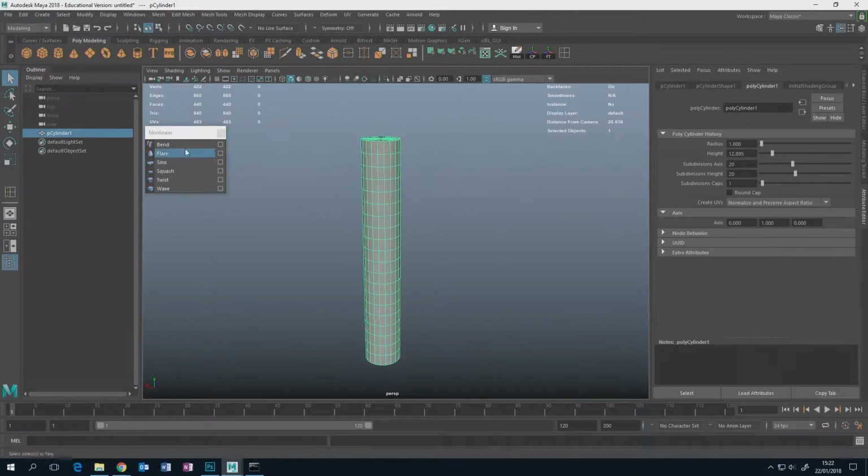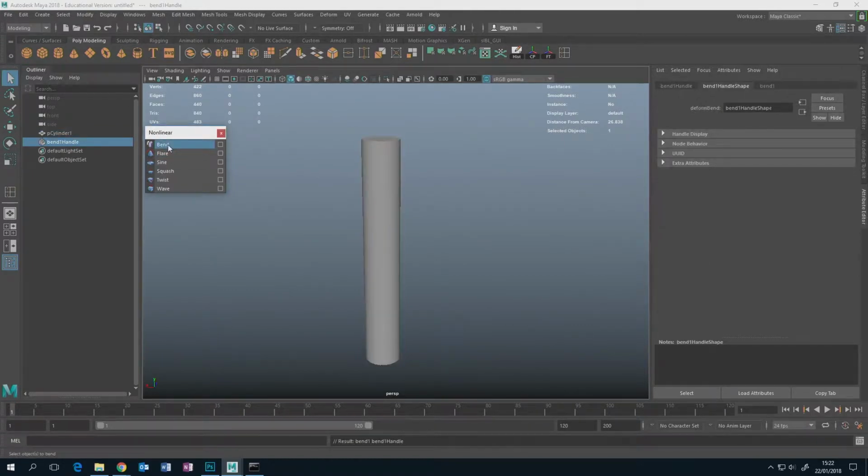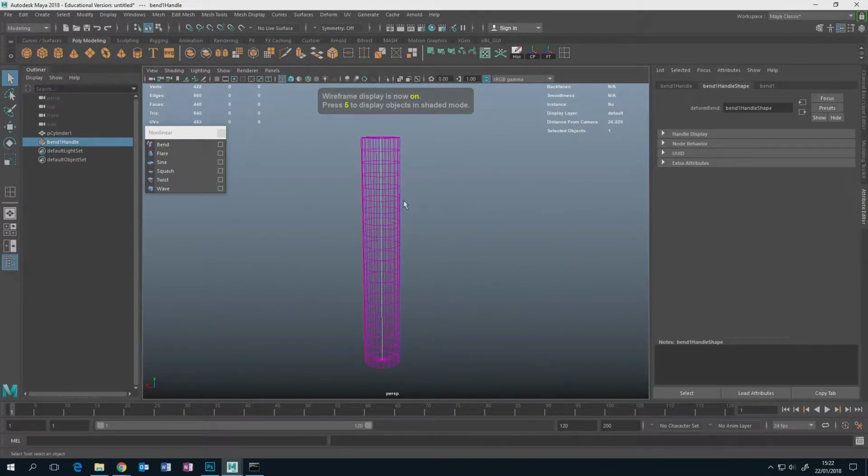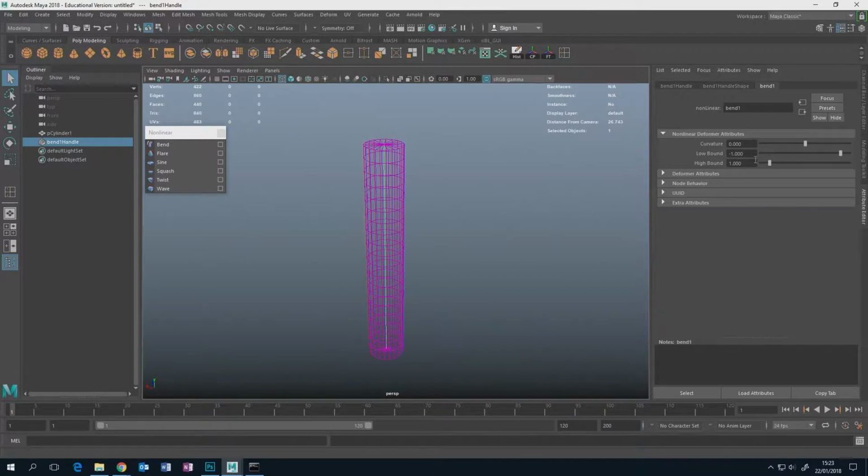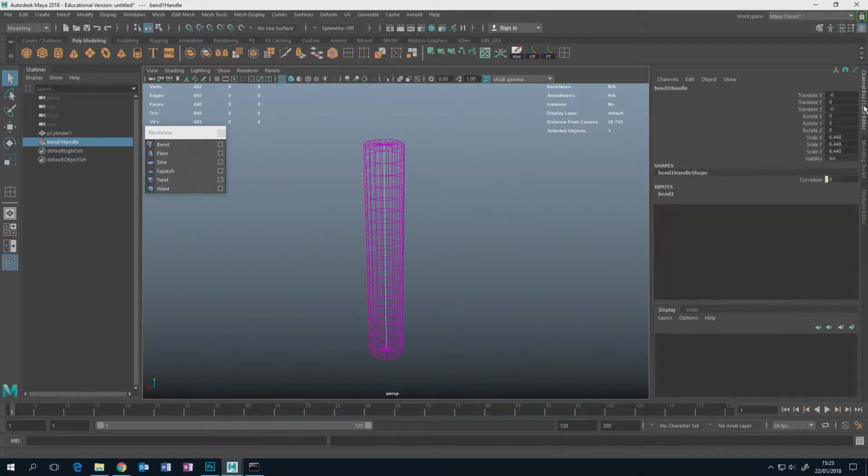The command for doing that is modify freeze transformations. So if I hit modify freeze transformation, it's going to zero out this stuff. I'll scale it as well to show you, because the one thing that's different is scale. Translate and rotate will be 0, but scale, its default state will be at 1. So I'm going to make that big. And if I want that to be the default state of this, I would go modify freeze transformations. But again, I'm going to hold down Control and Shift. It's going to add that little button. So I can just click that now, and that all resets.